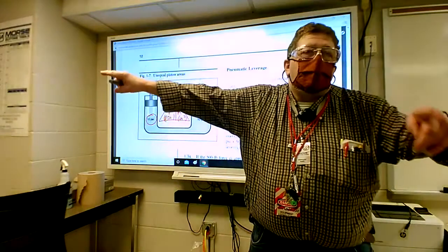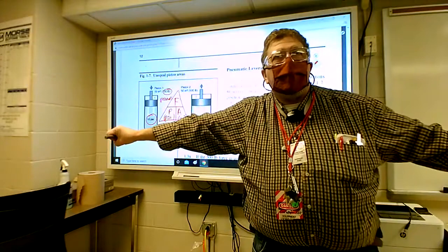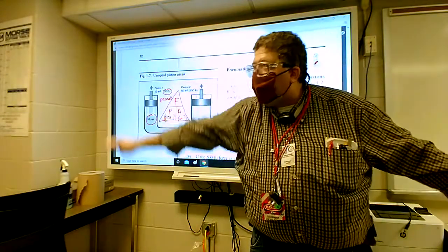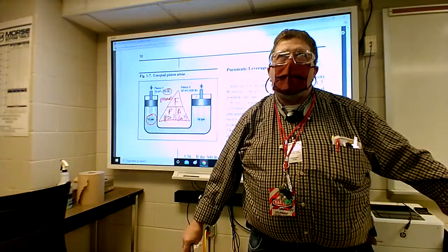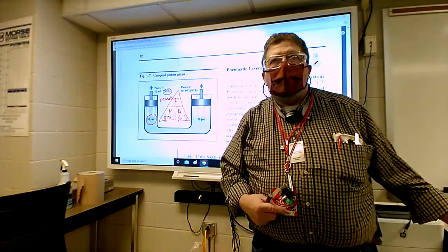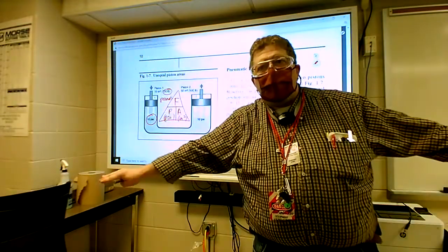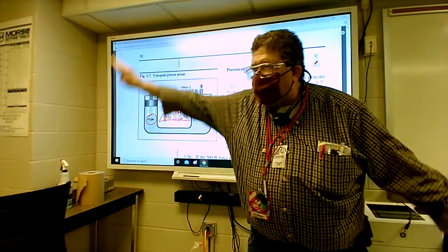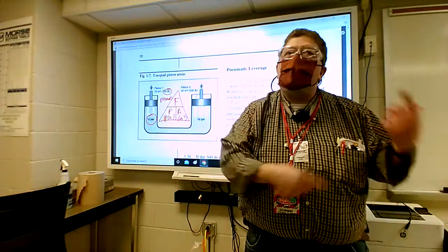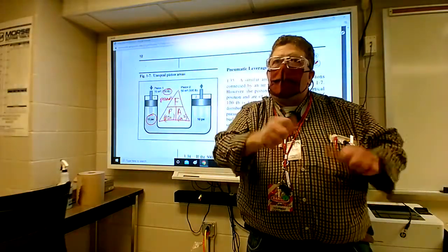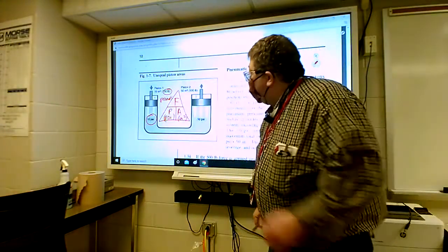Now tell me, when you pivot with that long cheater bar and you move that machine, if you move a foot over here, the machine doesn't move so much over there, does it? The distance, but yet you've got great power over it. You don't move it a lot. So the distance you move over here is decreased over there, but the power is increased the opposite amount. Your distance and your leverage are opposite when you get mechanical advantage.